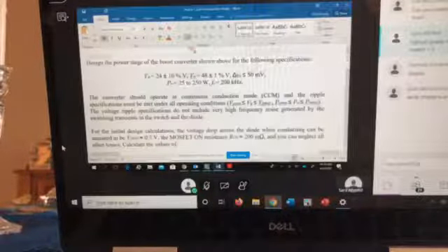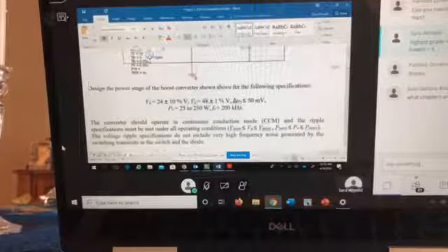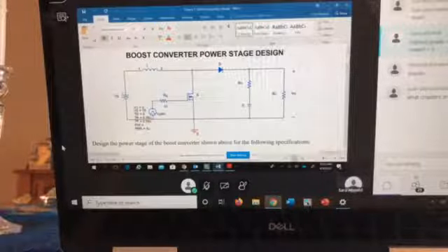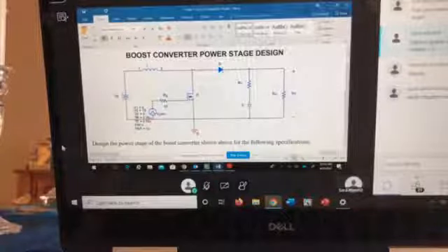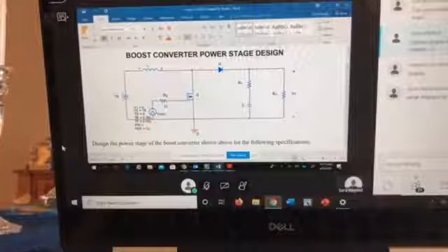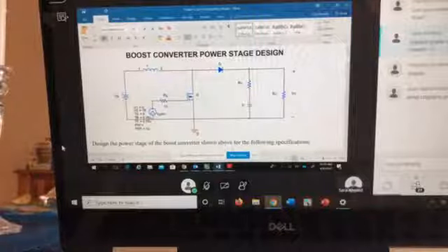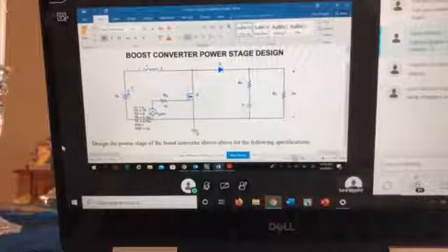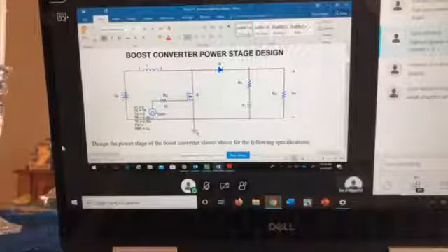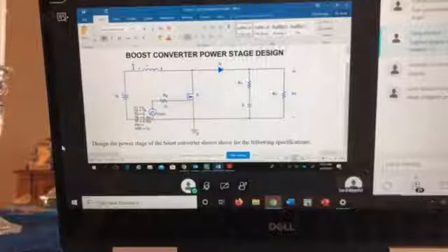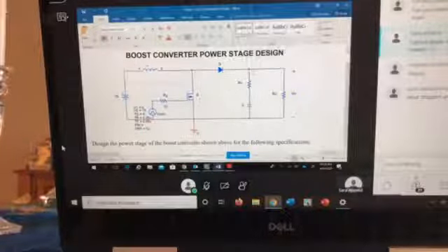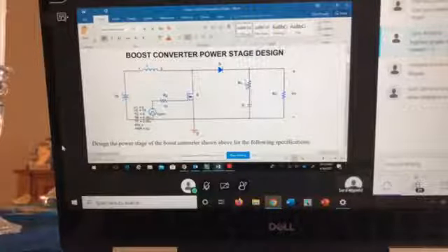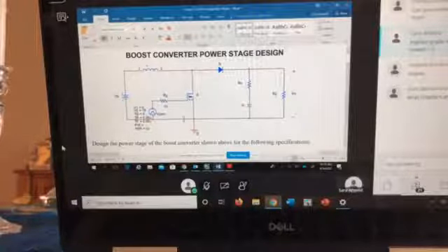So let's think a little bit about the specifications, and I want to make sure that you guys understand. You are designing a converter. What is the hardware part that you are going to design for? You are going to get a DC source and feed it as an input. This DC source, you can put in any value, right? But then your converter is starting from here. So you choose an inductance, a MOSFET, a diode, a capacitor, your RCs here. All of this you choose.